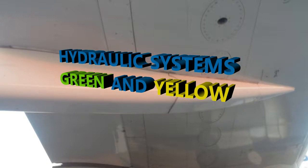What kind of information are they getting from the hydraulic systems? Well, you have 2: your pressure status and your pressure value. When we talk about value, we're talking about units of measurement, something quantified, a certain PSI, a number like 5,000 PSI. Hydraulic pressure status determines whether it's high or low.